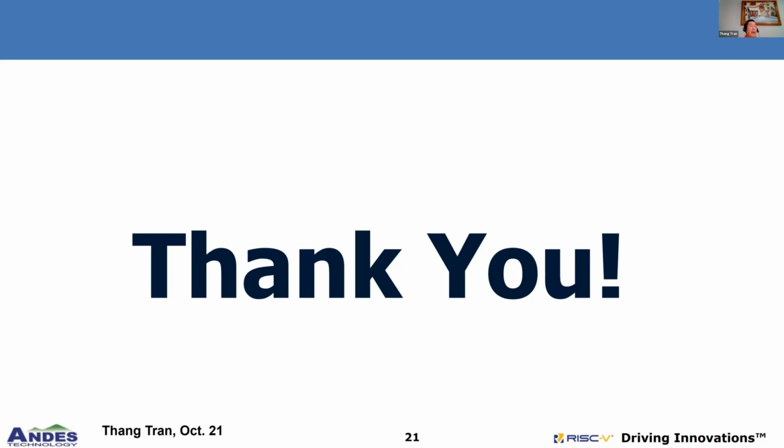In terms of power, we designed with 4-level clock gating in our design. And we also do not have any temporary register. So basically, the area and power is smaller because we don't have any temporary register, even though the design is out of order. That's also another point why we believe we have really good performance, because we actually do out of order execution and completion.